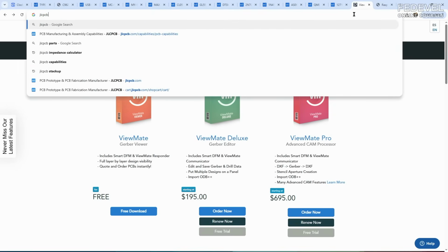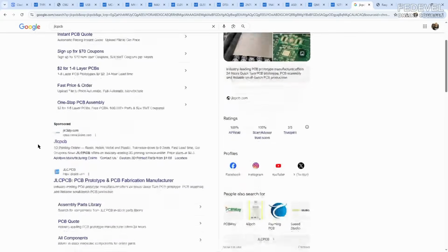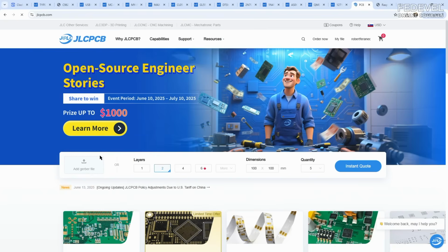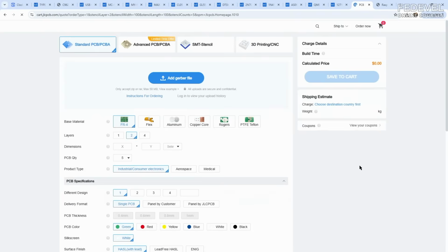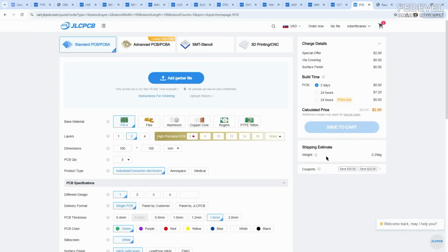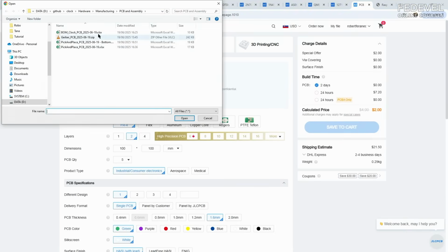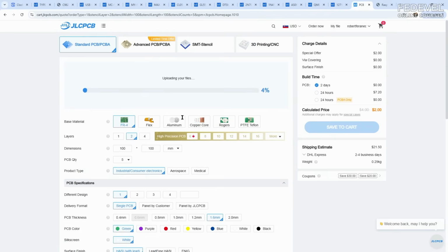Go to JLCPCB website. Click here, instant quote. Now here we are going to upload the Gerber files. So inside of our manufacturing directory, I'm going to select the Gerber files.